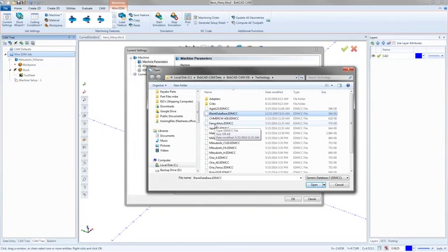You can add the database. You can try adding those things in. But whether the formatting is going to come out right and whether all those settings are right definitely depends on how much work's been done to the post. So if you do build a database, do some testing with it. If you're not getting the numbers and everything you need to output, talk to the posting and tech support guys and see what they say about getting that stuff put in.